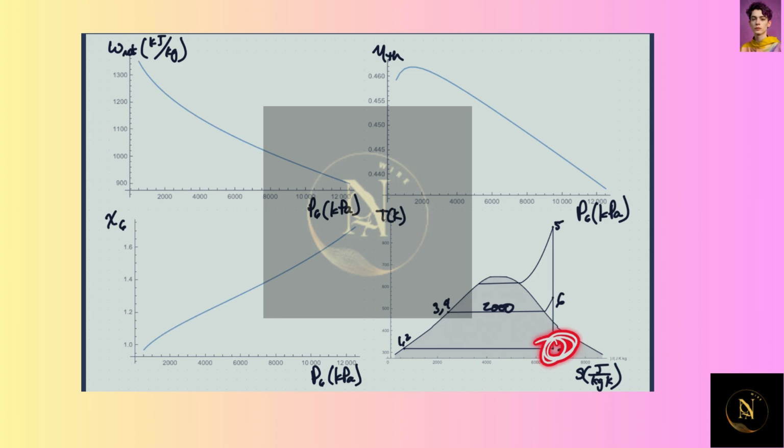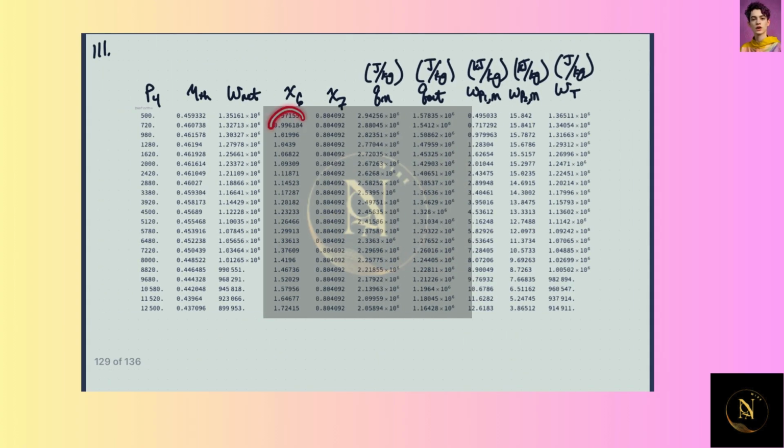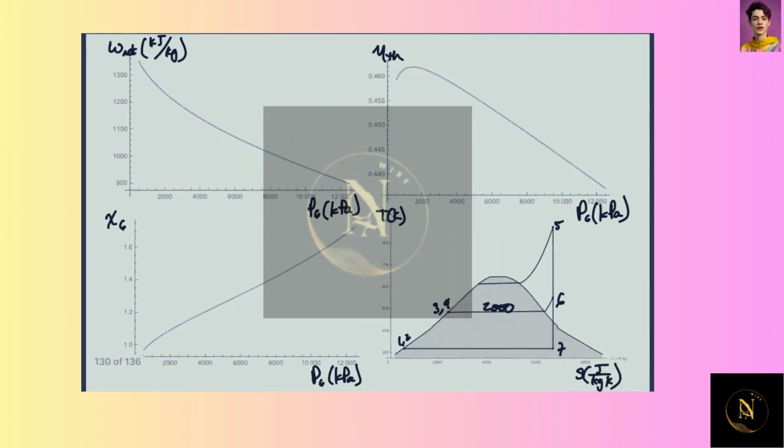Since this quality factor doesn't change at all, I just plotted this one here. And we can see here, all except for these very low pressures, way down, we are in supercritical. So again, we saw that just these two at these low pressures. And then, I can't remember, what did we use for the condenser? 10 kilopascals. So this was 15 megapascals, and this was 10 kilopascals.